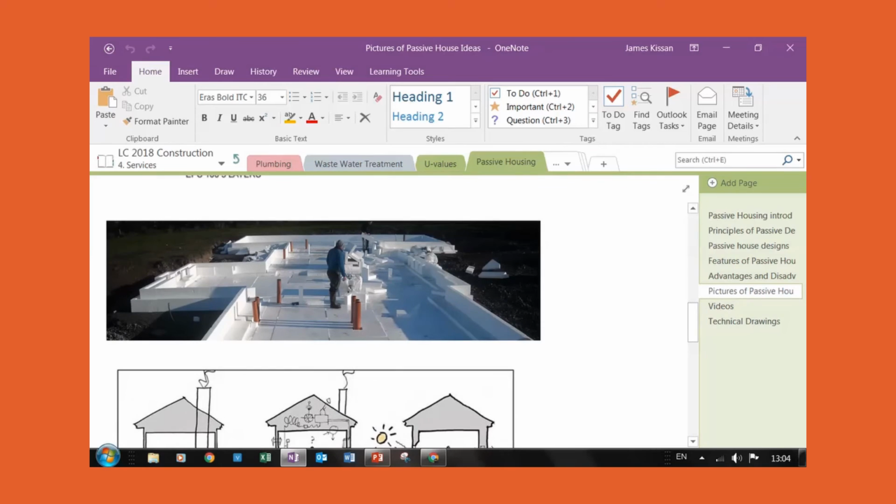Next, this here is what the building site looks like. Whereas if you're looking at, we'll say, a traditional building site, you'll see them taking away the soil, and the next thing then they do is they put in gravel, then they put the steel on top of the gravel, then they pour the concrete. Now what we're looking at in this diagram is you kind of start building it like Lego by placing in all this insulation, and then what takes place is we start pouring our concrete. But that concrete never actually touches the ground underneath. Now, this is all rigid insulation.